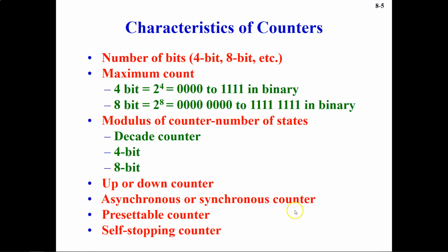Whereas in the synchronous counter, this has the advantage over the asynchronous counter, because in this one there is no increasing time delay. All flip-flops get activated in parallel, and thus the maximum operating frequency of this synchronous counter will be considerably higher than for the equivalent asynchronous counter.